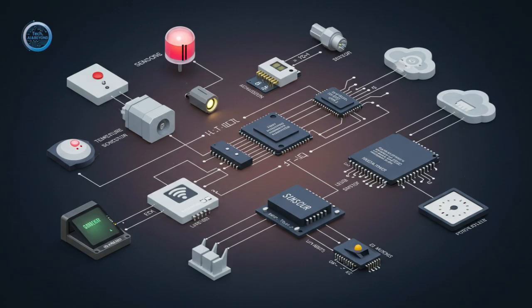A key feature of SPI is that it's often full duplex, meaning data can be sent and received at the same time because of the separate MOSI and MISO lines. It's commonly used when you need higher speed data transfer, like interfacing with SD card modules, faster graphical displays, or some types of sensors that produce a lot of data quickly. Faster, four wires, good for high throughput.